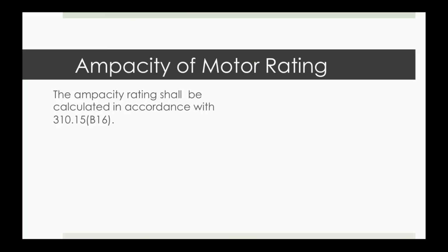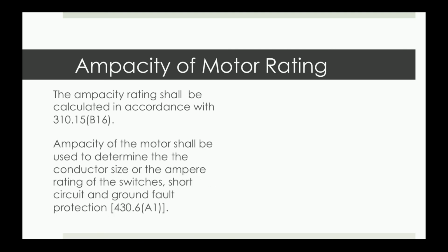Capacity rating of the motor. So the ampacity rating shall be calculated in accordance with 310.15(B)(16). This is what we use to size electrical conductors, and it is also used for motor circuits or conductors as well. The ampacity of the motor shall be used to determine the conductor size and the ampere rating of the switch or switches, short circuit, and ground fault protection.